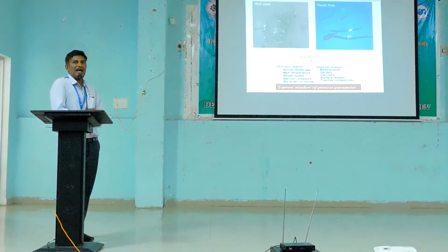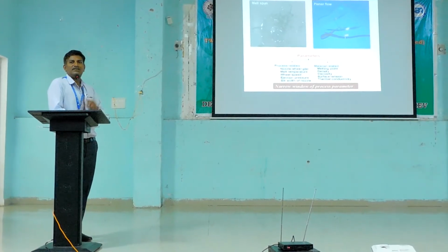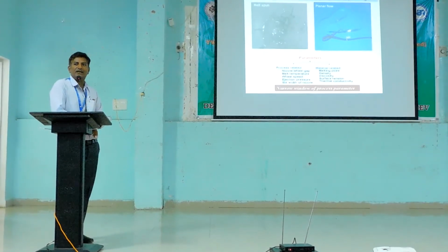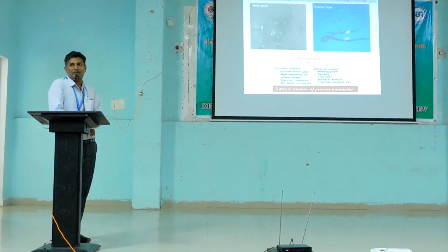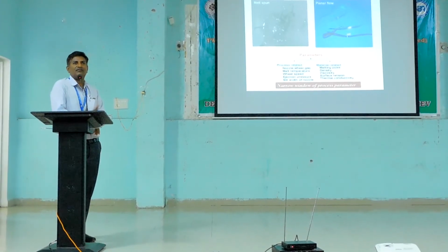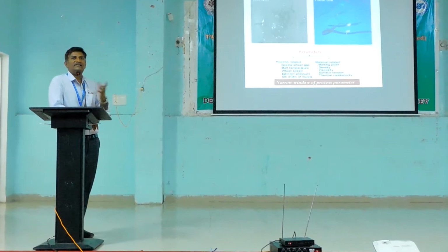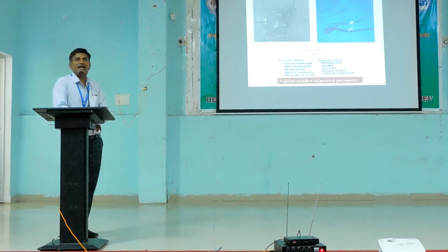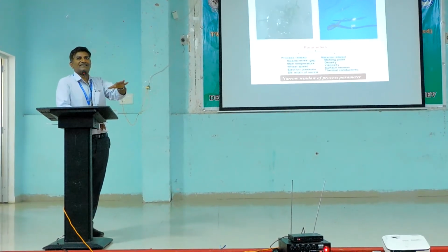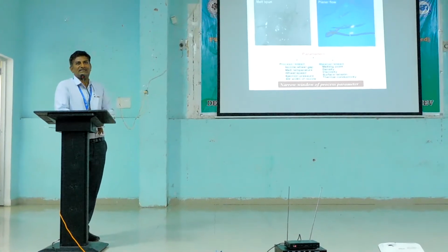Have you come across any transformers? You know what a transformer material is? What is the transformer core made up of? CRGO steel. What is CRGO? It is basically an iron silicon alloy. It is grain oriented in one direction, and the direction is along the easy axis of magnetization.